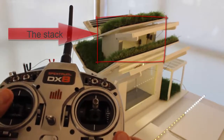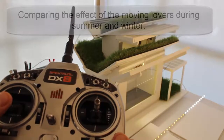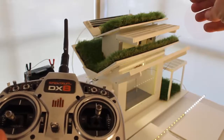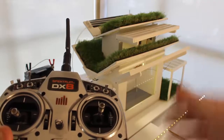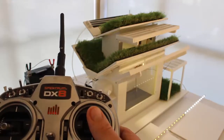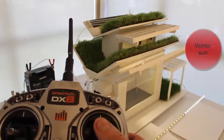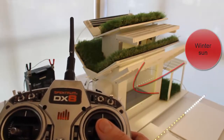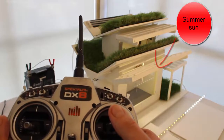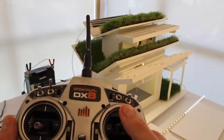However, during summer, the louver would move down, and as the sun sits higher in the sky now, we can adjust the angle so that it would screen out the sun and keep the building cool. The other alternative or option is where the lower louver can also move up and down, and again it will be up during winter so that the sun can get into the building, but lower during summer to screen the sun from the building. So we don't want the sun to shine into the building and heat up the building, because we want it to be cool during summer.